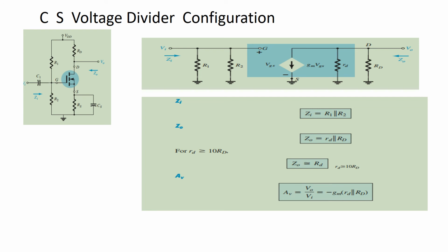So when you are finding out input impedance, what is required is the input voltage source and the actual resistance between the input terminals. So you take a ratio, or you take a product of these two resistances as they are in parallel, R1, R2. So input impedance is nothing but equal to the parallel combination of resistances R1 and R2.